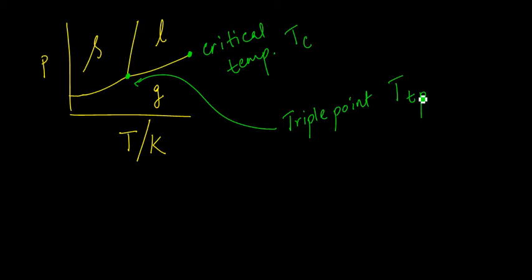Remember, the earlier temperature scales were based on the boiling point of water or melting point of water at 1 atmosphere. But the atmospheric conditions can change, right? And then your boiling points would change, or your melting points would change. Melting points not so much, but boiling points definitely more. So this triple point is what we say invariant.